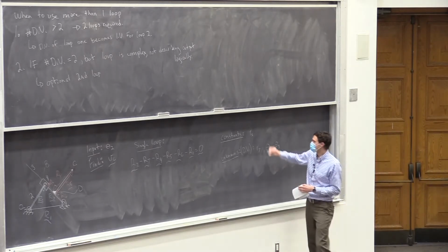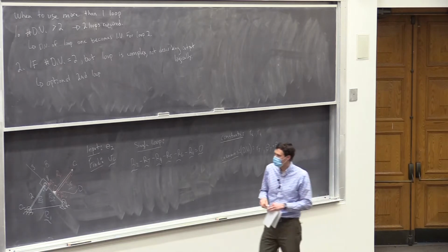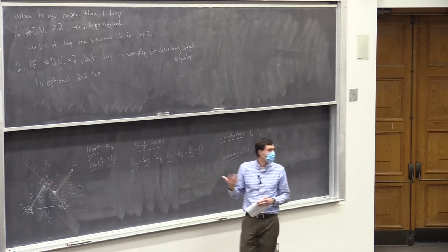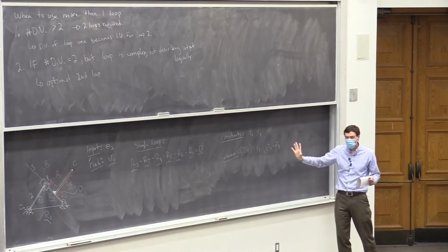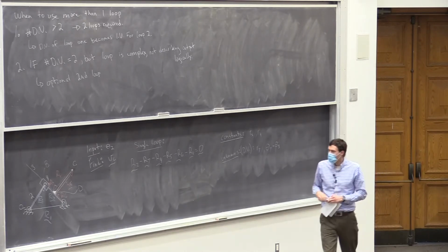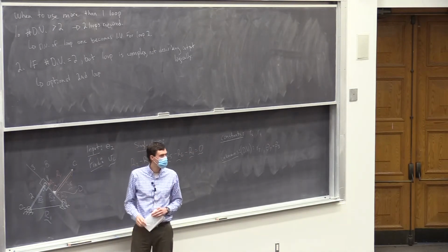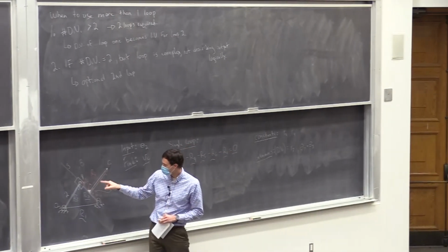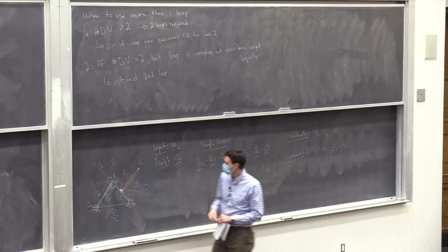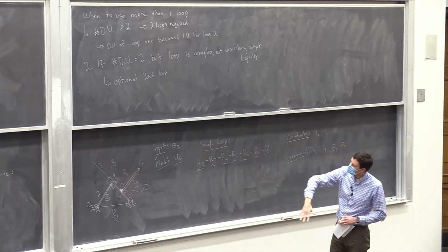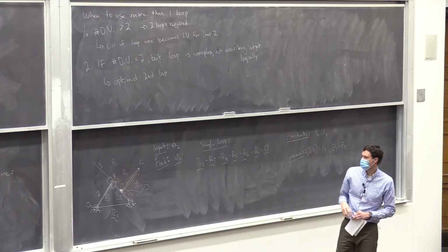So 4 has a constant length. But what about its angle? Its angle varies with length 3. So you may be tempted to put it as an unknown. And you could, if you didn't know anything about it, you could put it here. Or you could notice that it's always perpendicular to 7. Right? That's the design of length 3. If you know theta 7, you know theta 4. It's just, what would it be? 90 degrees more, right? It's 90 degrees counterclockwise.